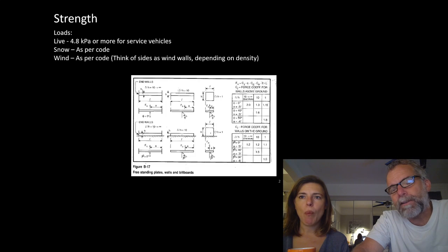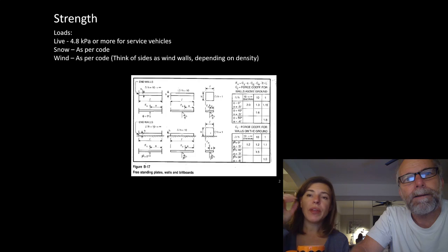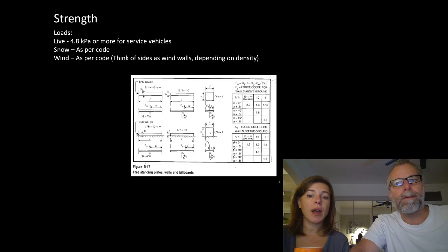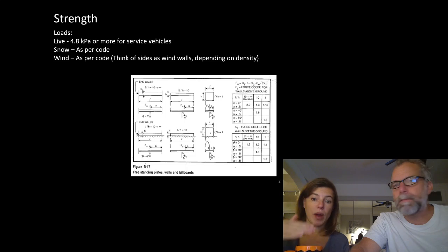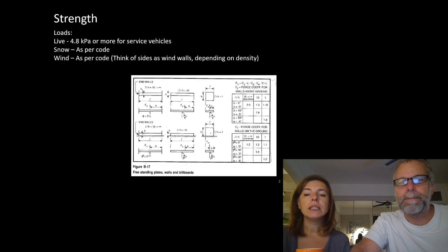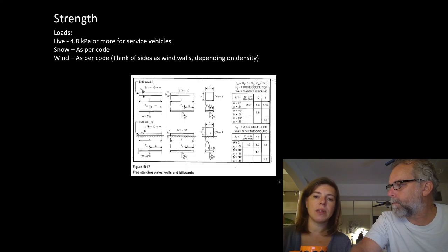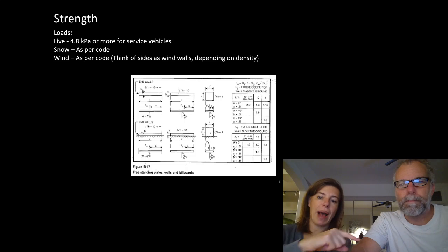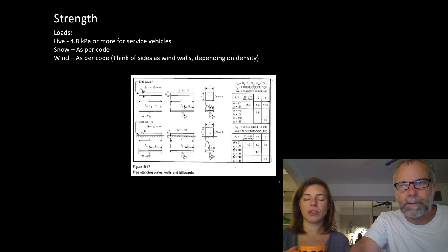And then the last two are H and L. That's just the projected area of the bridge. And the one thing that this equation doesn't show, which I made sure to show you in the guard portion, where I showed this image and wrote out all of those things Dave just mentioned, was the importance factor. So IULS and ISLS needs to be in that equation. They don't show it in this because it also references this back to the main equation, and it says that you need to include that even though it doesn't show it in the writing.